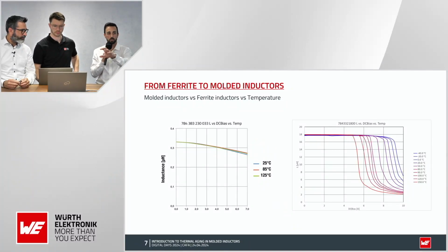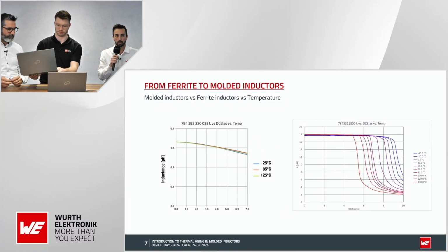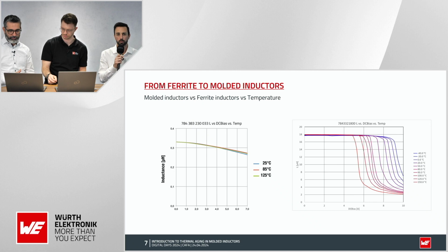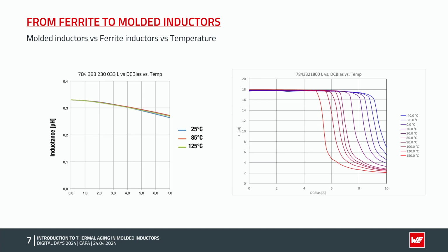Yes, every product we release into the market, we prepare all this information we said to you for Red Expert. We can offer you these different saturation curves. Maybe I will go back, it will be easy if we can see it. So you can enter your expected temperature of your application, and you can check if at 150 degrees it will be suitable for you or not. You don't need to pay so much attention if you select a molded inductor. And also regarding the AC losses, for sure, we offer all of this available in Red Expert for free for every single part number we release into the market.